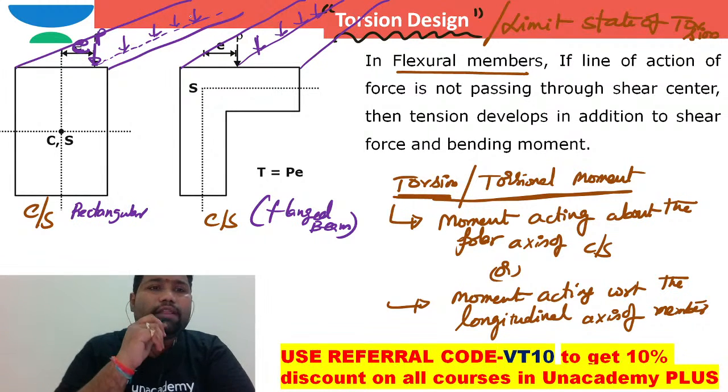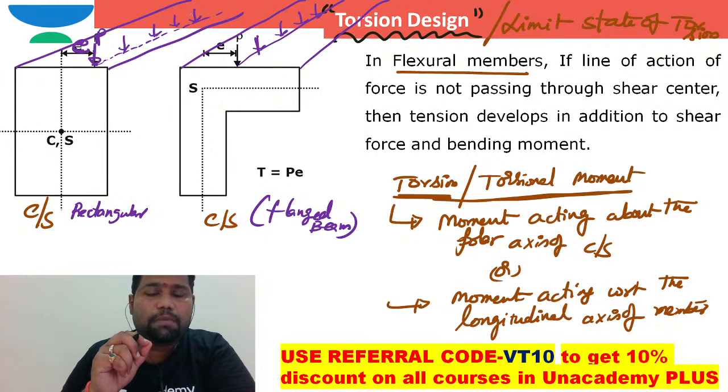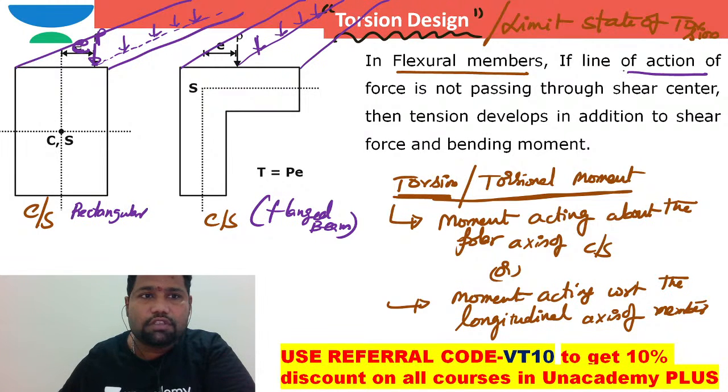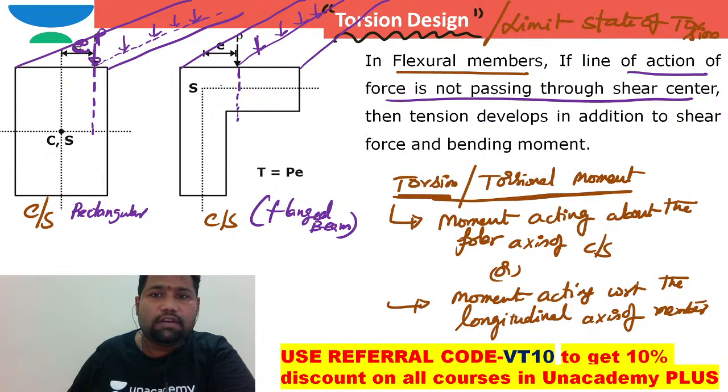Right. Now, when this torsion is developed on the cross section, brother, if this is the force, this is the line of action of the force, right? When the line of action of the force is not passing through the shear center, then torsion develops in addition to shear force and bending moment.